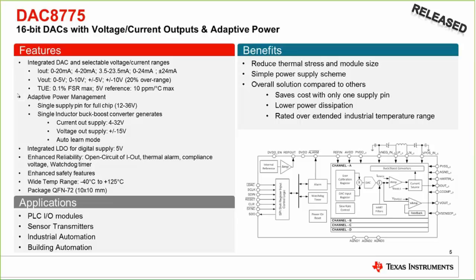In the end, we're not really providing much of any information on what the load is. Again, really the principal purpose is to drive current or voltage into a load. I guess you could maybe try to use clamp mode and the current output readback to detect what kind of load you were driving along with the compliance voltage alarm. But it would definitely not be 16 bits of resolution to detect load impedance.